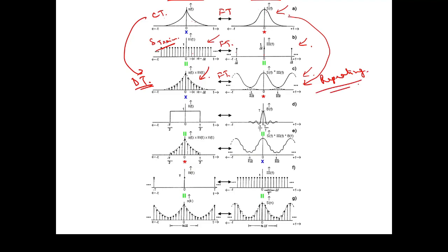The original frequency component is repeating itself. Why? Because in the time domain we have multiplied, however in the frequency domain it gets convolved. Okay. For calculating the output of the LTI system, we saw that convolution was in the time domain and multiplication was in the frequency domain. So the vice versa also happens.